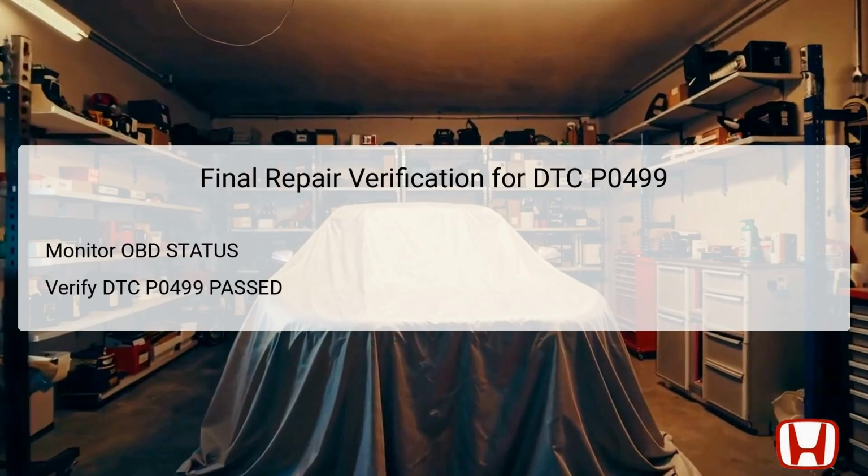The focus here is to check whether the HDS indicates that DTC P0499 has passed. If it confirms a successful pass, it suggests that no further issues exist with the EVAP system or its components. If the DTC still indicates a failure, further troubleshooting is mandated, including checking previously repaired connections or further diagnostics for